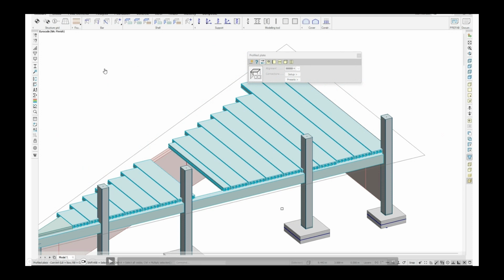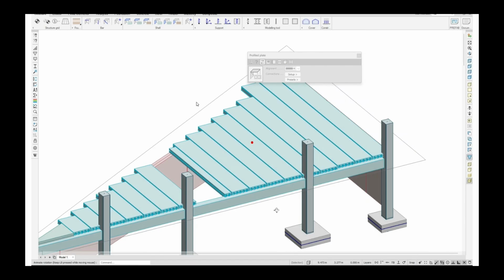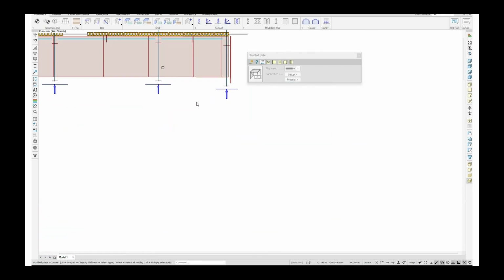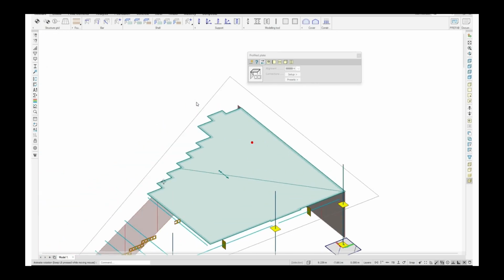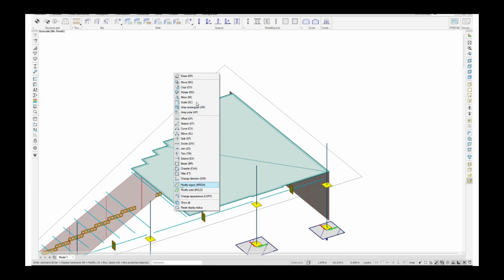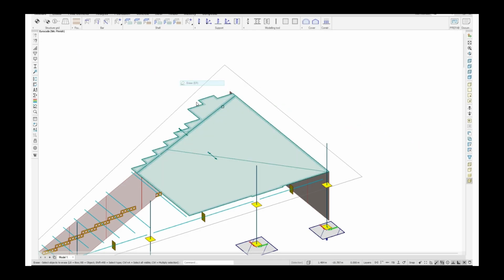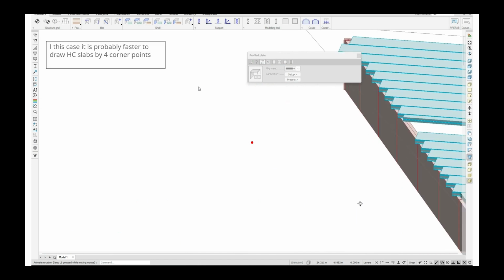If you look at this model, it's not so obvious that it is reasonable, because now they are beams, and a beam doesn't have any angled or inclined end. So the problem is that if we convert those, and by the way, first align everything to the plane, otherwise it doesn't work. So we have to use correct model before you use this one. And then we have to, of course, cut it like this. And then you can just use the alignment tools the normal way to align everything together. But it's possible, but then you have to understand whether it is even worthwhile to do.